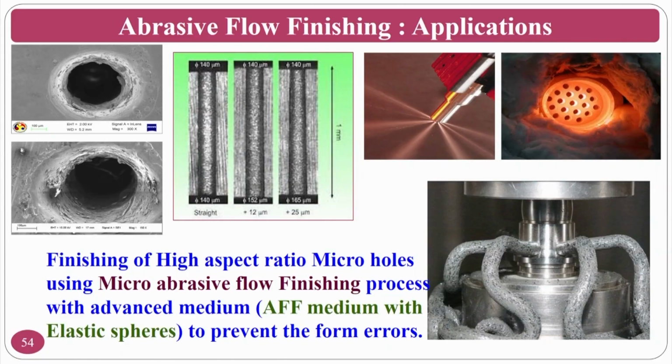Okay. You can also do finishing of these laser machined surfaces, because if you can see here, these surfaces are thermally destroyed surfaces. These layers will have recast layers, heat affected zone and many other zones.